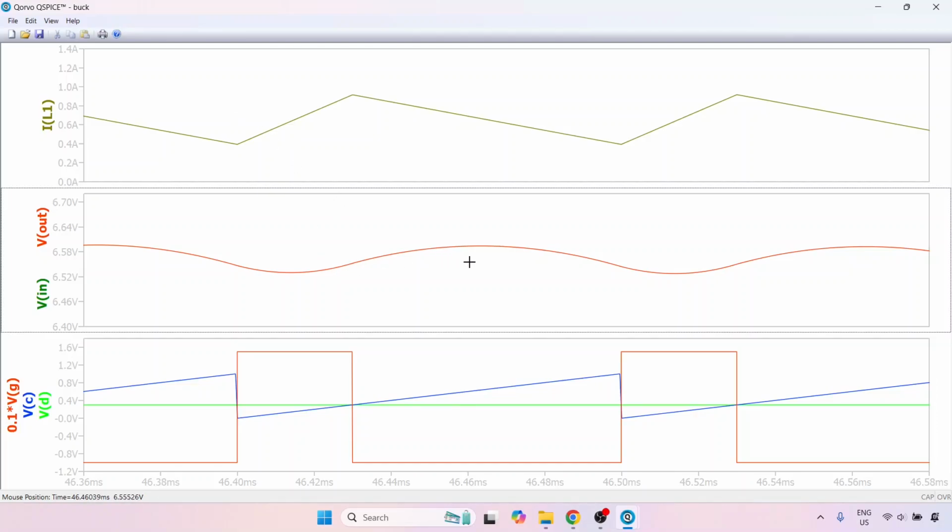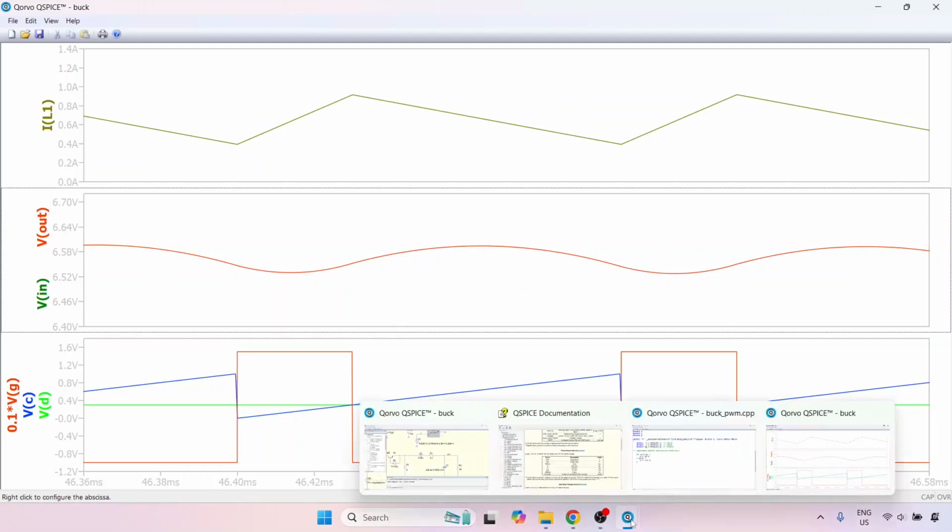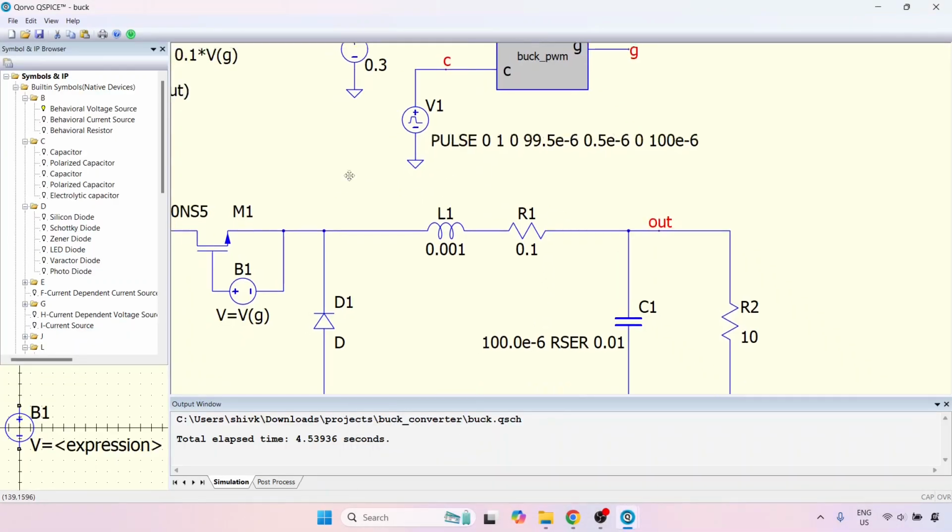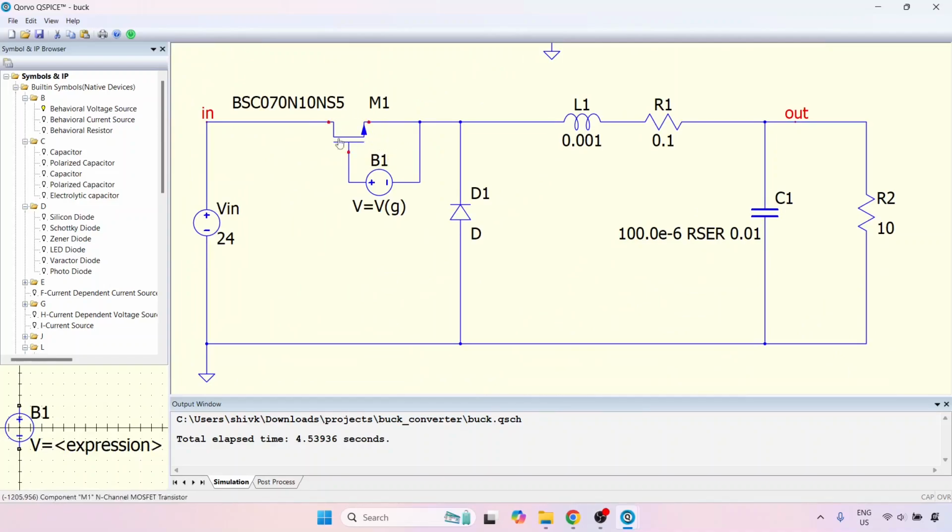This is the essential concept of any power electronic converter, which I will continue to emphasize throughout this course. That is, because of using nonlinear elements, we are using a MOSFET. This MOSFET can only operate in two conditions, the cutoff region and the saturation region. That is, either it is conducting and it is a negligible resistance, or it is not conducting and it is an infinite resistance, or a very large resistance which is as good as infinite.